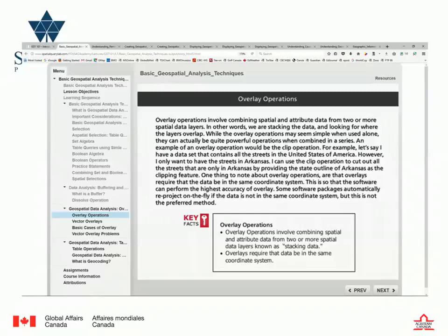For example, you have one layer in UTM zone 47. You have another layer in lat long. You have your project coordinate system in UTM 47, and you enable on the fly. What you will see is the lat long layer displayed in UTM 47, but the data is still lat long. The coordinates are still lat long. So if you try to do an overlay, it won't work.